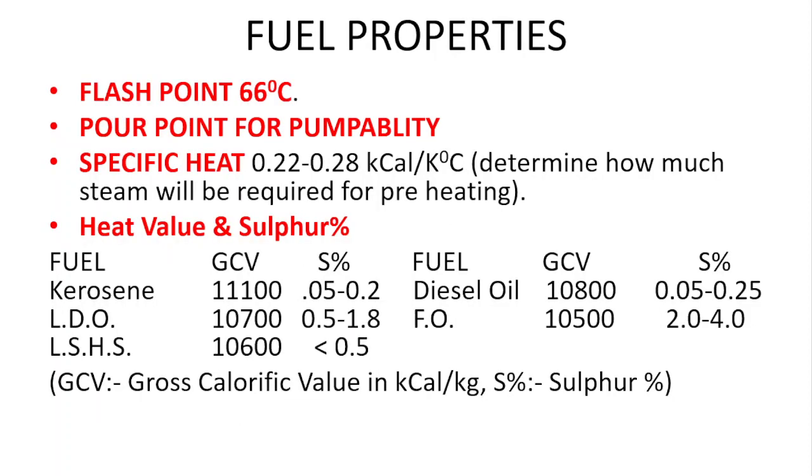The flash point is also one of the properties of the liquid fuel. Pour point is for pumpability, and the specific heat is also a property which will determine how much steam will be required for preheating. Then the heat value and the sulfur percentage of liquid fuels.